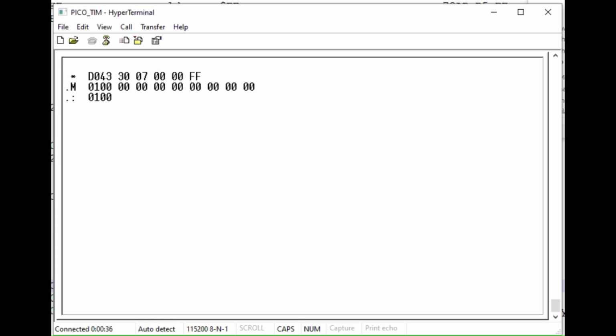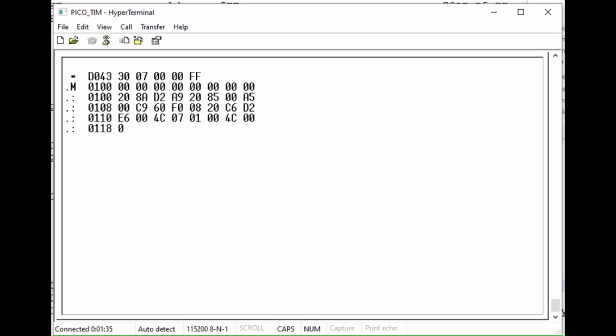Let's try entering and running a program using the TIM. I'll enter the character printing test program included in the TIM manual, with the modified character I/O routine locations and run it. After entering the program, I'll change the program counter to the beginning of the program and then type G to go. As expected, all characters are output to the terminal.